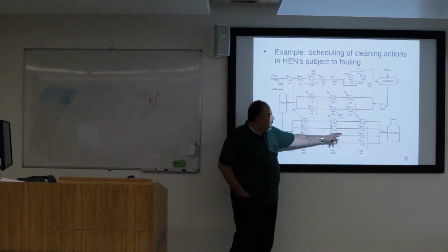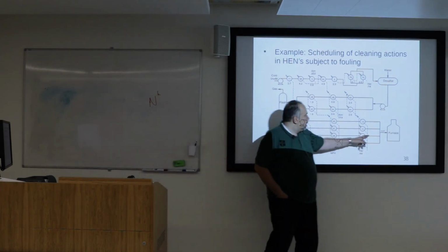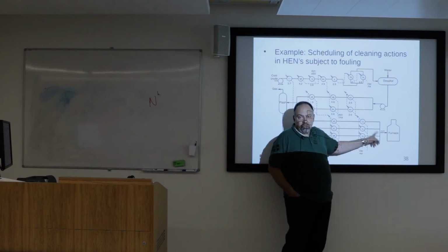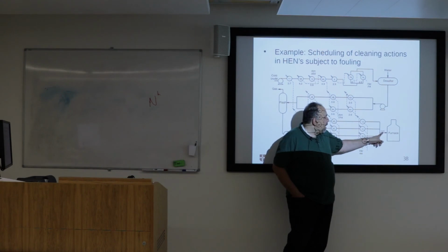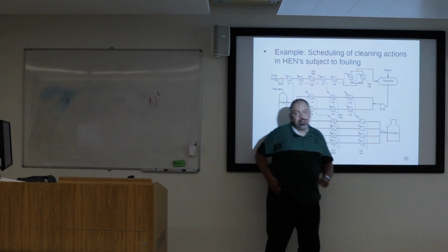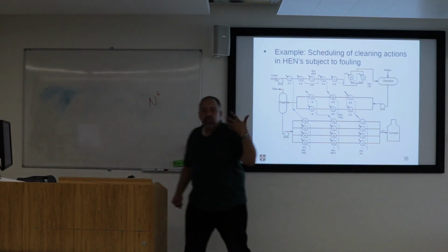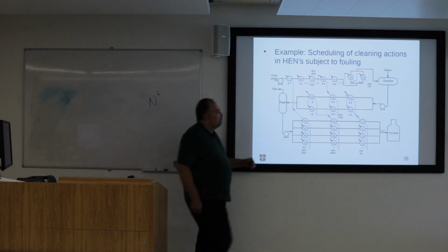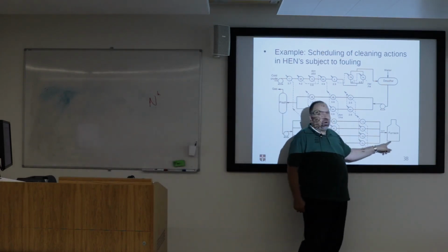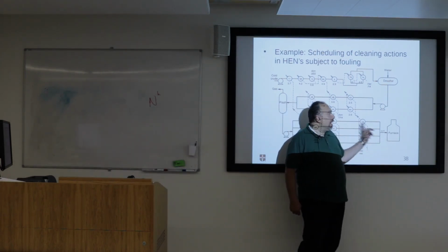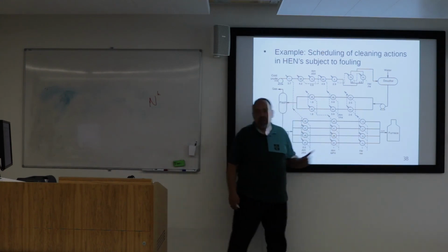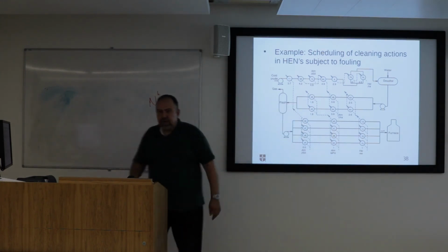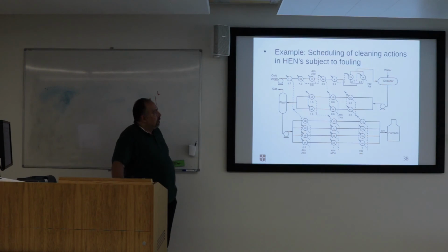And eventually, you want to maximize the energy recovery with this integration so that you have the maximum entry temperature into the furnace, because then the furnace has to give you a fixed set temperature for the first distillation column. So the lower this temperature is, the more energy you have to spend. So you have to have good performance of the heat recovery network to work.